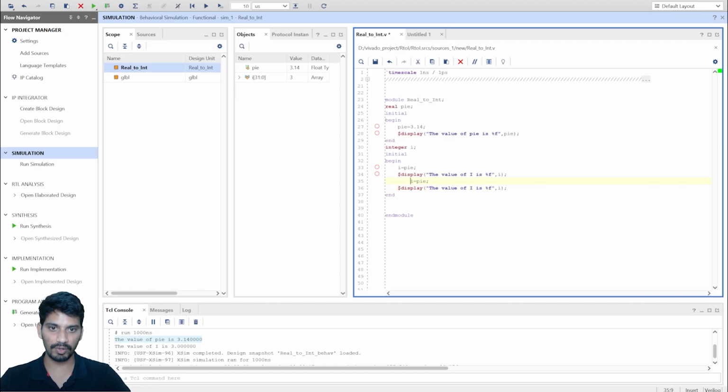but I want to assign i to some different value after, let's say, 100 nanoseconds delay. So this is a delay function. The hash symbol defines a delay of how many nanoseconds? 100 nanoseconds. Even though this is not synthesizable, I was writing in the stimuli file, so it is okay to do the simulation. But unsynthesizable code like delay functions is not implementable. I will explain what synthesizable and non-synthesizable code is in future slides. But right now, consider this as a delay element.